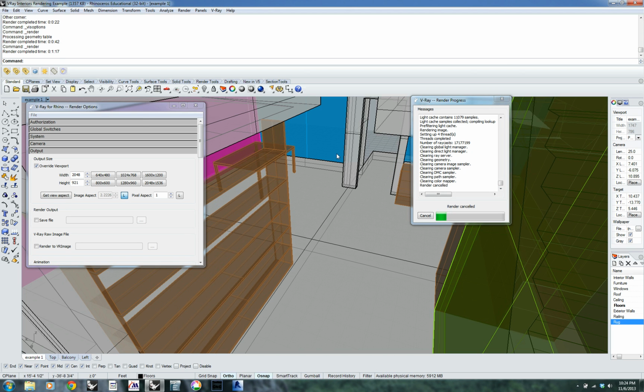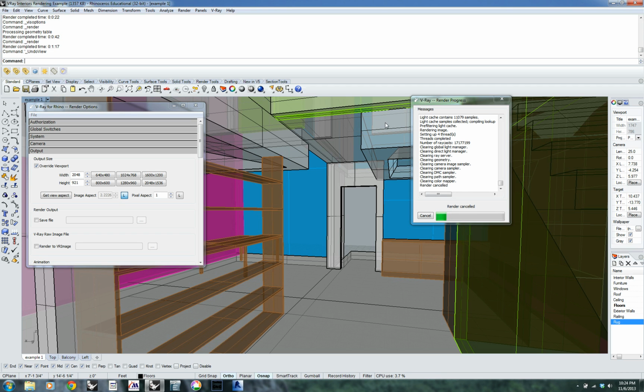of exactly the view that I want there. Click on this undo view change, and it'll bring me back to the last view. So I'm going to be getting a render of exactly this viewport. That's usually a good idea. Also, if you decide that you want to overlay any line work over your rendering, the best way to line it up is to export the viewport from your Make 2D effect and also from this render, and make sure that you're always using that viewport, the entire extent of your viewport, and then those two images will line up.